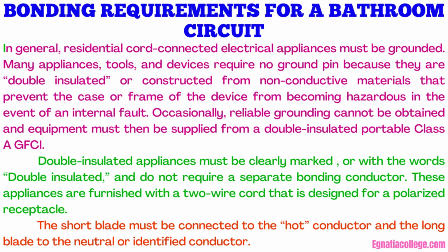These appliances are furnished with a 2-wire cord that is designed for a polarized receptacle. The short blade must be connected to the hot conductor and the long blade to the neutral or identified conductor.